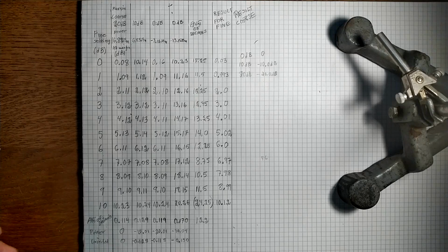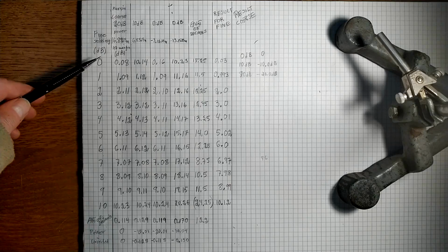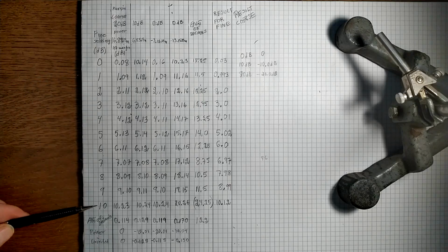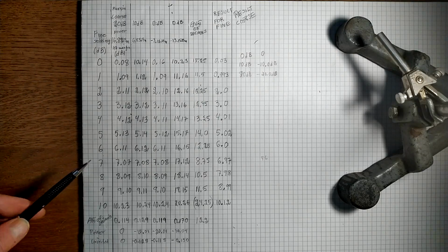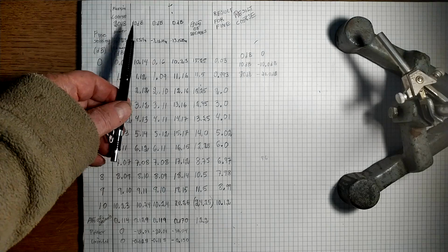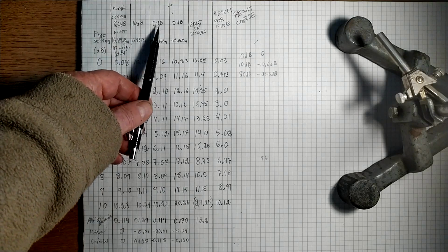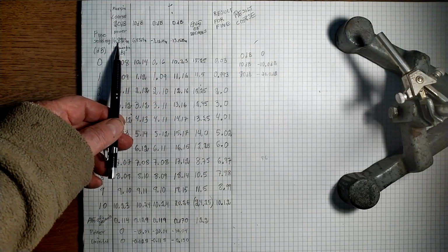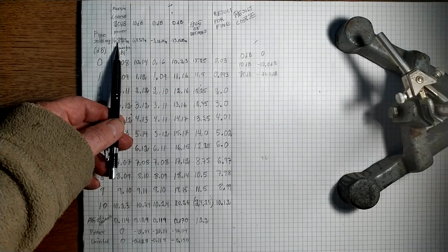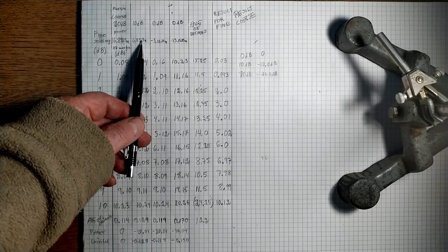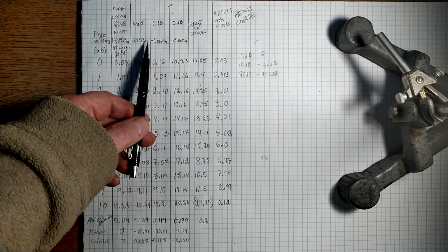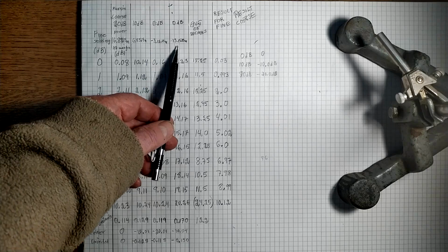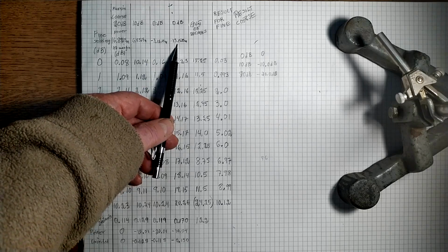I have tested all combinations of 10 dB stepping and 1 dB stepping on that attenuator. So 0, 1, 2 and up to 10 for the fine, and then 20 dB, 10 dB, 0 dB, and then 0 dB once more. And the power level is different each time, differs by about 10 dB: plus 16.89, plus 6.88, minus 3.12 and minus 13.15 dBm.